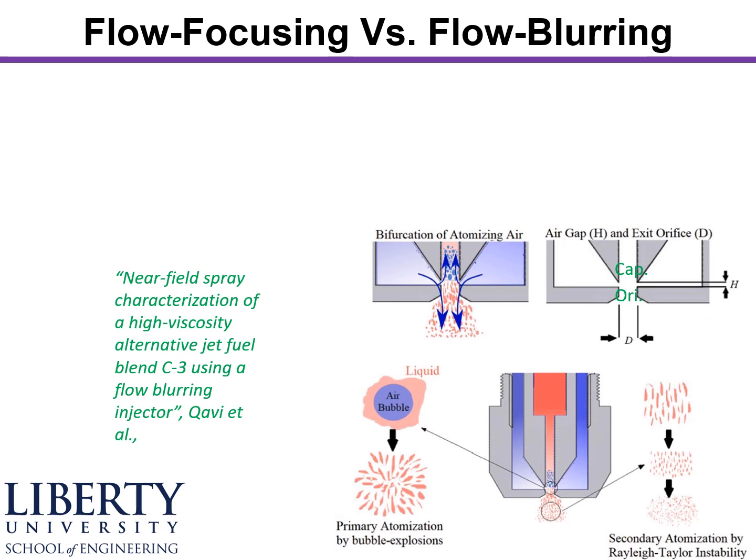Is the capillary diameter, which is what the liquid path involves, and then the orifice diameter, which is what occurs after they meet, and then the height h between them. But if flow blurring does occur, and I'll describe the transition here in a minute to some extent, when flow blurring occurs, you see that the gas penetrates the liquid phase, and in fact, depending on the nozzle orientation and buoyancy, the gas can actually pass